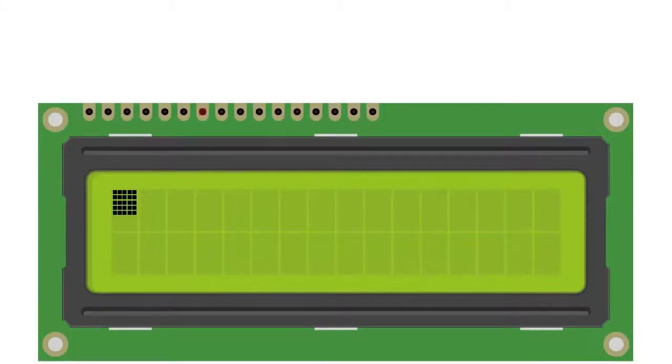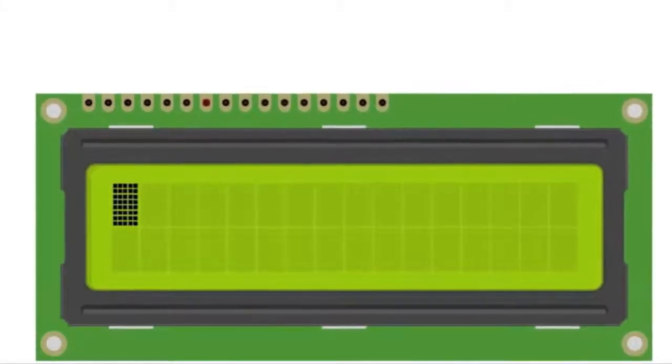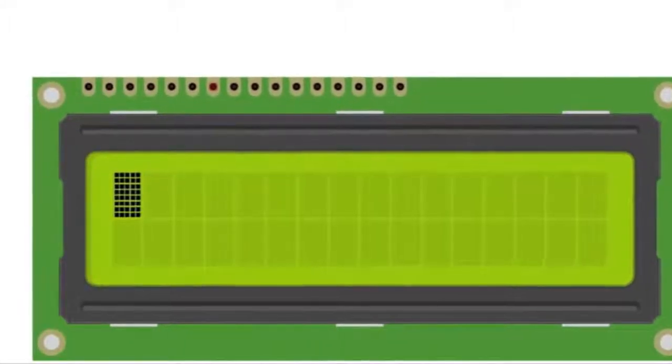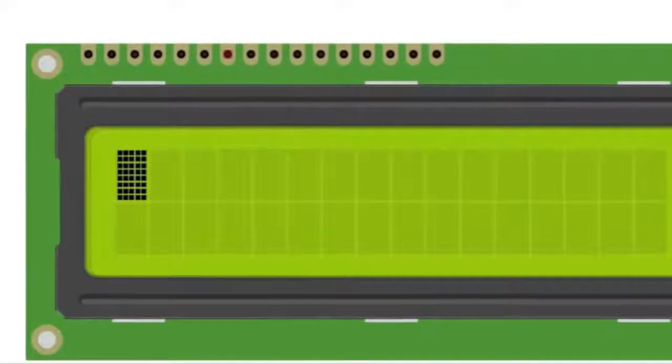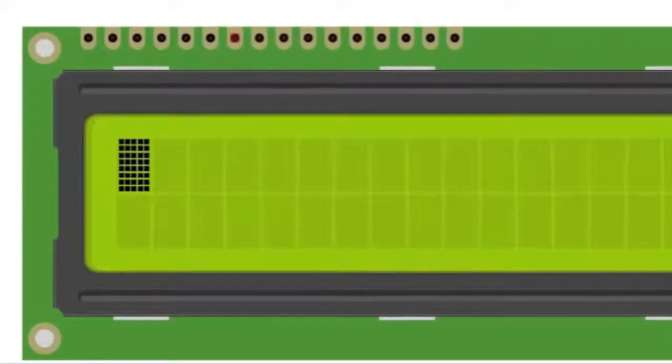If you think of each character on the LCD as a block of pixels rather than a unique symbol, then it's easy to see how the characters are formed. Each block is 5 pixels by 8 pixels, but the bottom row is usually left blank, to leave room for a cursor. LCDs like these, with the industry standard Hitachi controller inside, can support up to 8 different custom characters.